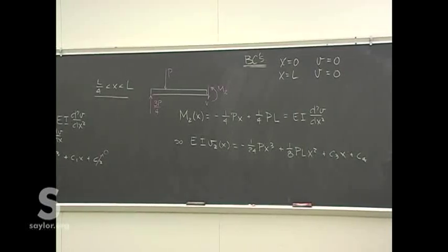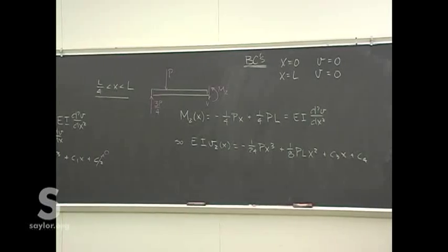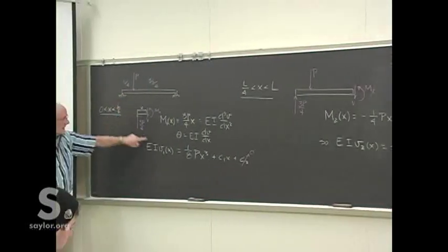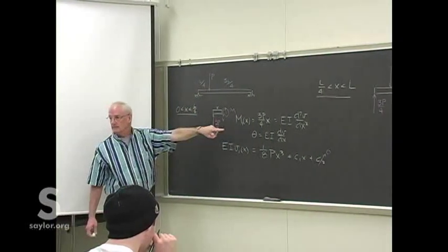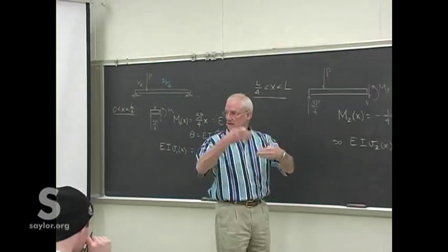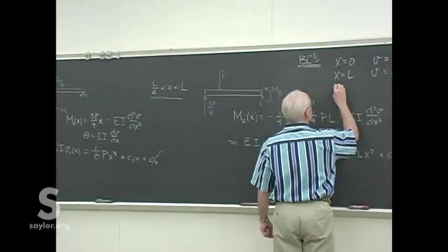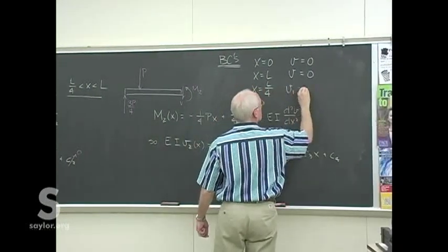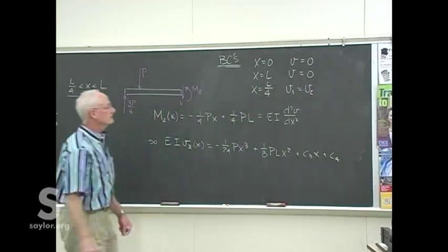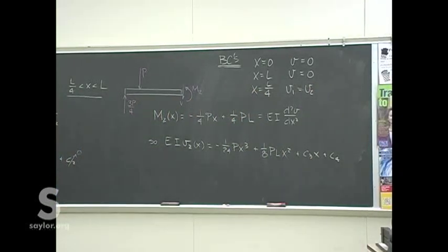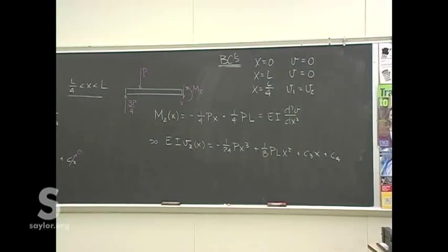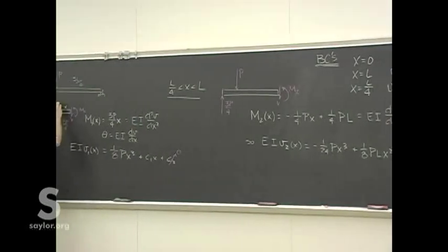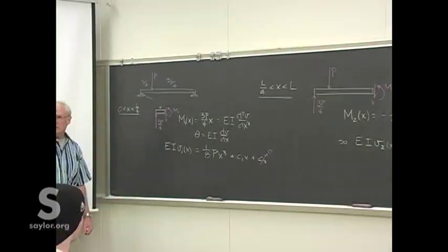Travis, one of them. At x equals L over 4, the graphs are equal. At x equals L over 4, we want V1 to equal V2. If not, the beam is sheared and has failed, so we don't have any problem after that. V1 equals V2. That just ensures that the beam itself is continuous. We wouldn't want the deflection to come down one place and then be disjointed as it finishes the curve.